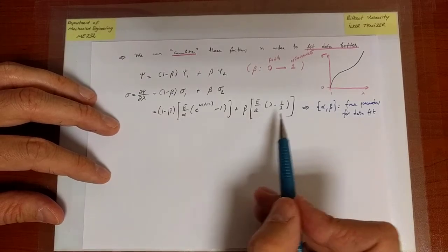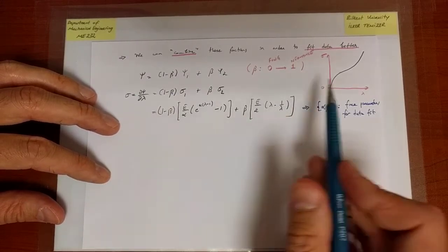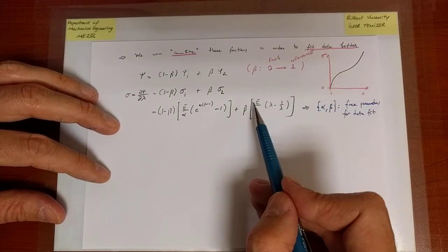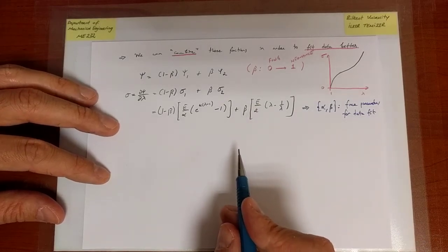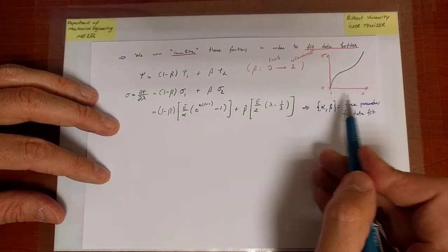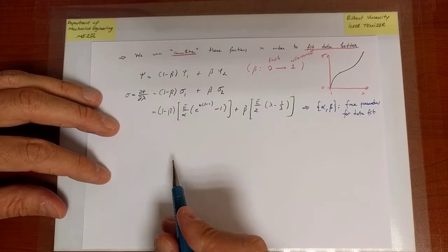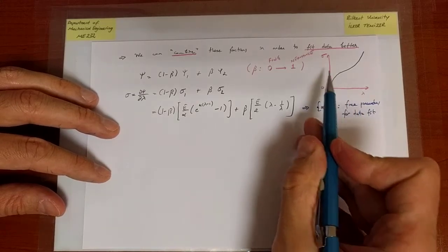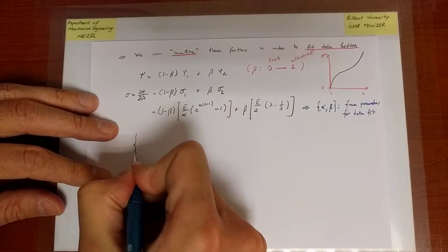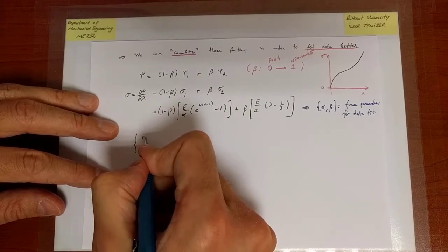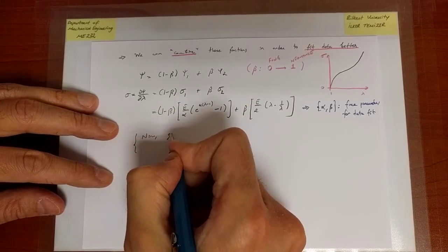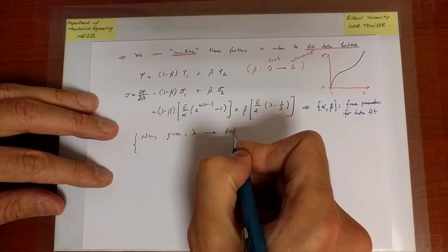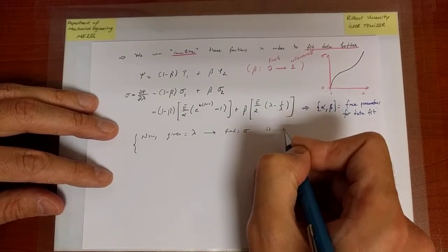If you go ahead and plot the stress versus stretch behavior, it's going to qualitatively look like this, but the exact view is going to depend on the values of E, beta and alpha, and also the range of lambdas that you choose to plot it for. But remember always what we're trying to do. You give me a value of stretch, and I'm trying to calculate the value of the corresponding stress. That's easy. That is one practical engineering concern: the deformation is given and you want to find the stress, and that is easy.